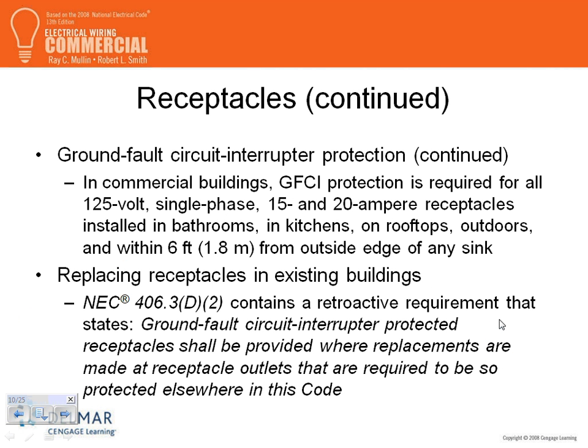A couple of things where this is important, because this is commercial, guys. Where do you need a commercial GFCI receptacle? I thought this is really interesting, again from an article, I can't recall which article. I want to emphasize that we're only looking at 15 and 20 amp, and Spencer, we're only looking at 120 volts. So if you have a 15 or 20 amp, 120 volt receptacle, here are the locations that you need GFCI in a commercial building. Very important.